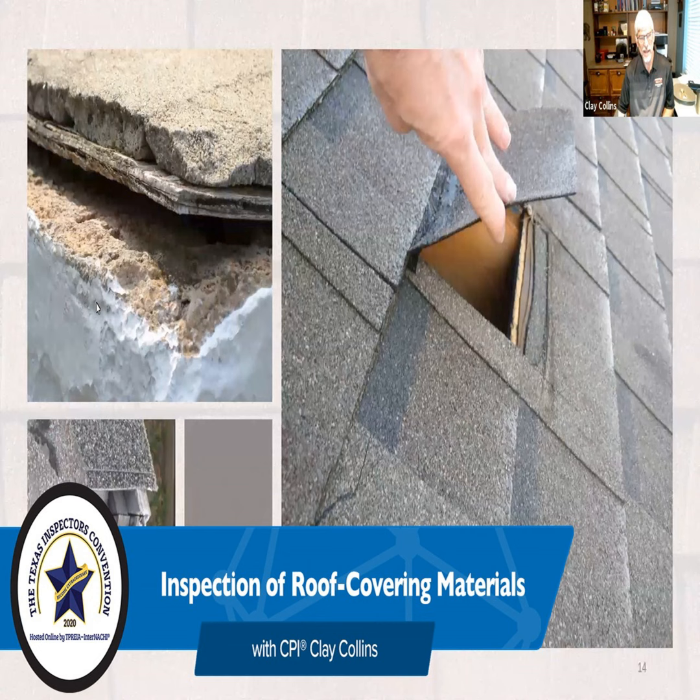The special techniques down here on the 1 1/2 to 16 would include that underlayment overlap that we talked about. When you get down into this lower slope, that's the roll roofing.